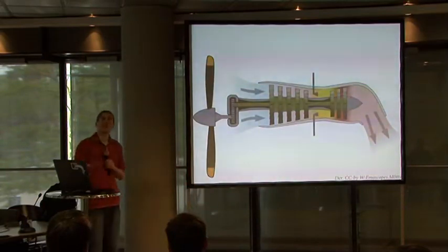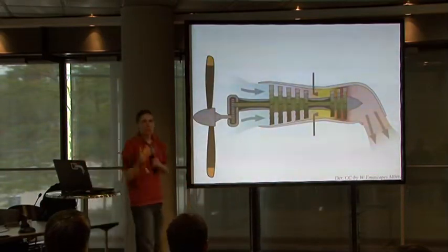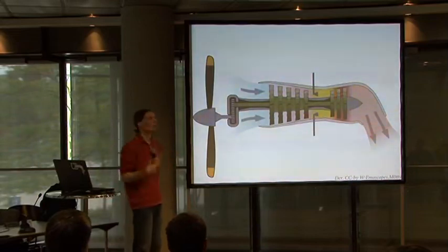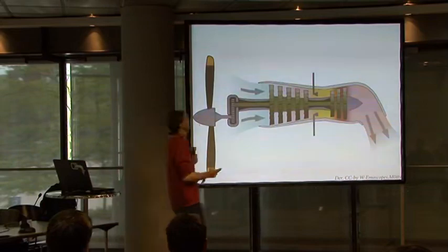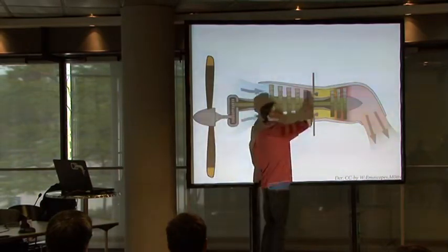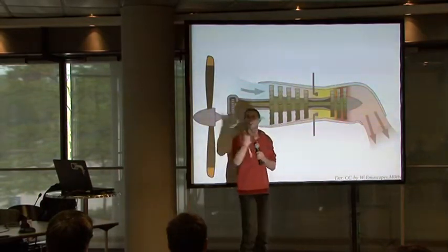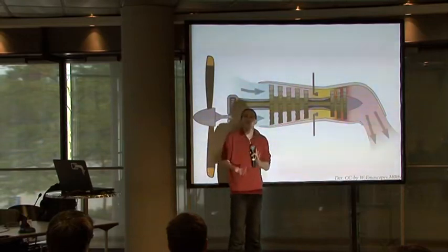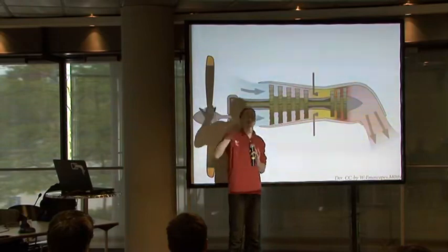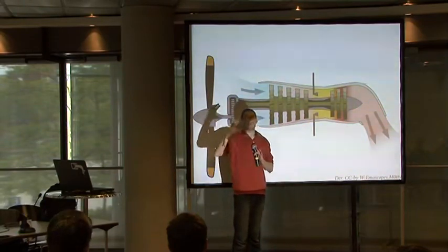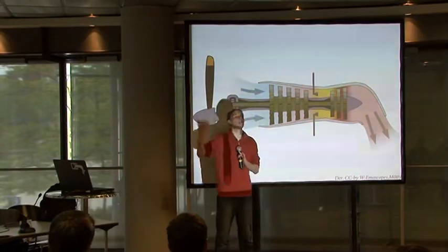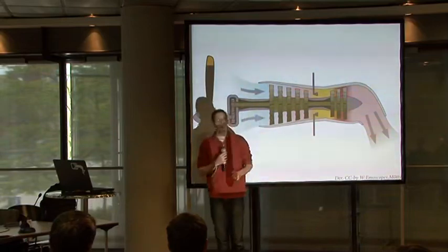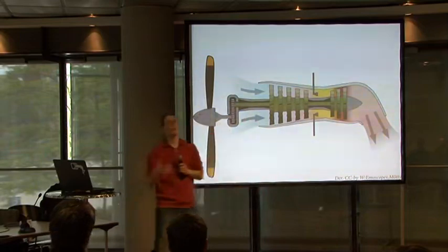There are many ways to mitigate this effect, and the biggest trick or hack that we bring to engines to try to mitigate this effect is to compress the gas before we add heat. So typically in the jet engine, in the car engine, before the combustion, we compress the gas to raise its temperature. So the higher the temperature of the gas, we sort of prepare it to accept new heat in the combustion process.